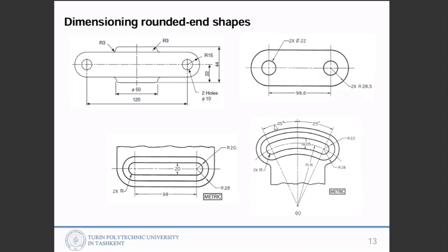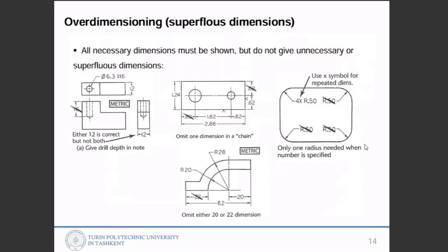And here 25 to the left hand side, 25 to the right hand side, and we have the radius, and then from the center radius 116, 116, and the distance between them is equally like 190.5, so like a bean shape. And then here the radius 2x or something is given.